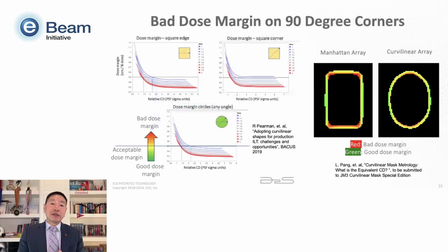Well, it's very similar to lithography. In lithography, we talk about process window. We know process window has two variables. One is dose, the other one is focus. For mask writing, there is also a process window, but because an eBeam has an infinitely long depth of focus, we don't really have to care about the focus, but we really care about the dose. The dose can actually change. So in lithography, we call that dose latitude. In mask making, we call that dose margin.